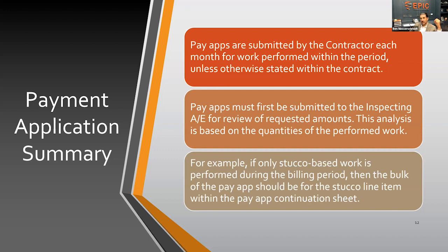Any crack injection, any reinforcement cover correction, any full slab or partial slab repairs, and those have associated individual bidding quantities. Whether you can forecast those bidding quantities, if there's going to be any destructive work or evaluation work done by the engineer prior to, or if estimates are just placed on there by the engineer or the owner's representative, it's important to have more detail than not.